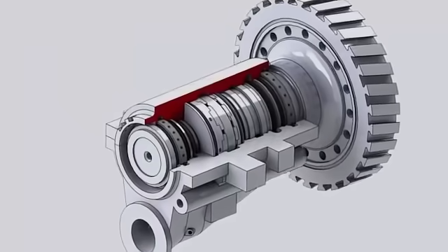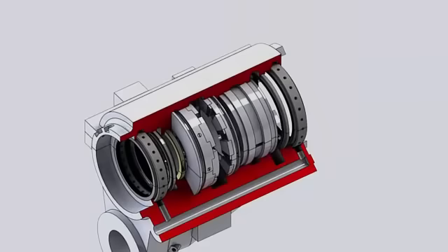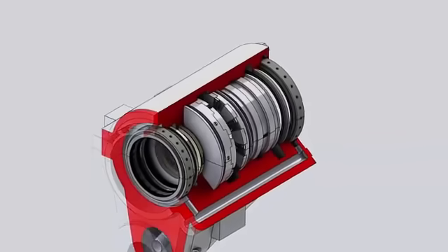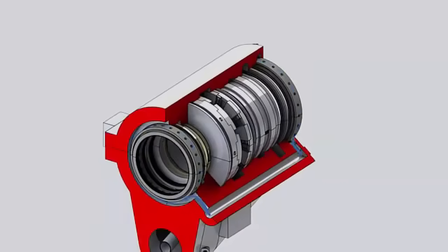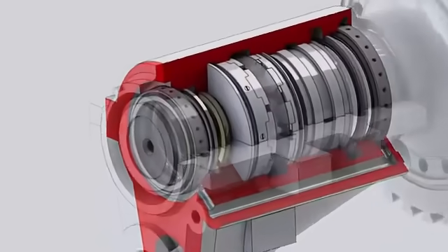The sealing airflow from the cooling and sealing system flows through the axial tube machined at the right side of the housing and is admitted to the labyrinth seals through 2 ports to annular spaces surrounding the seals. Between the 2 rows of seal teeth, sealing air is admitted through multiple radial holes to stop oil from spreading along the shaft. Some of this air returns with the lube oil and is vented through the lube oil mist eliminator, and some escapes out of the housing.